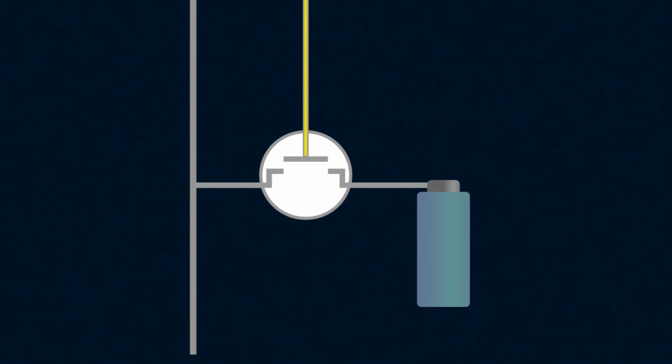As a reminder, it consists of a capacitor and a transistor, as well as contacts connecting the cell to the circuit. More precisely, there are two of these contacts. One is attached to the transistor's gate, and depending on the presence or absence of voltage on it, it is determined whether the transistor controlling the cell is in an open or closed position. The second contact is connected to the line leading to the capacitor, and through it, reading and writing of data from the cell is carried out.